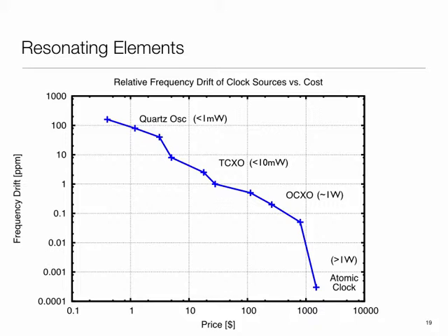So let's imagine that I want to time an incoming event and then wake up, or I want to wake up at a certain designated time. Now if I'm maintaining the time with a lower granularity, the precision with which I can do that task is going to go down. If in sleep mode you need to either timestamp something or wake up with a very fine precision, then you are in a bit of a dilemma.